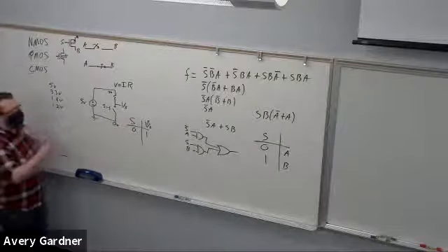So if there's a resistor, that resistor has to take the same amount of voltage as the supply. So we go up 5 volts here, and we lose 5 volts over that resistor. If I had 2 resistors, and I don't know the values of these resistors, I can't say how much voltage is there. But what I can still say is over those 2 resistors, I must lose 5 volts.